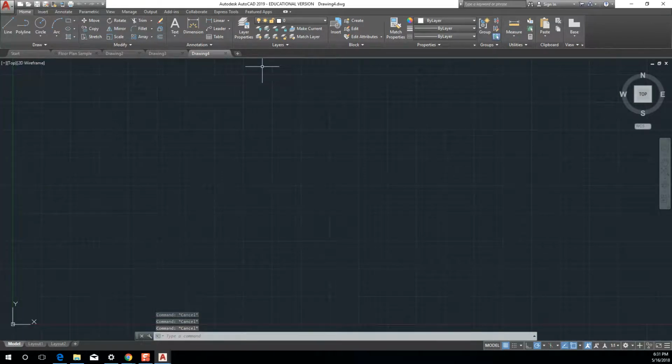The escape key in AutoCAD, in Revit, it's the get out of jail free card, right? If I get caught in a menu, I hit escape and it clears it out, right? Emma's laughing like, yep, that's exactly it. If I get in a command and I don't like the command, I hit escape and I get out of it, right? Escape will clear out any command that you're in, just by hitting it.